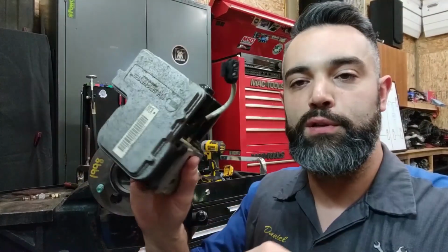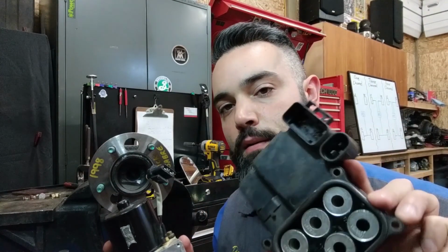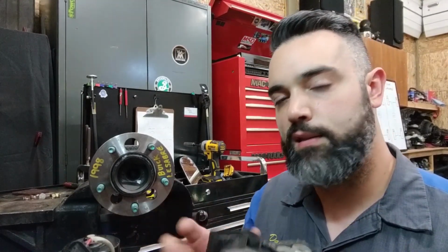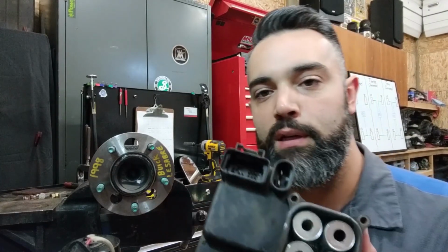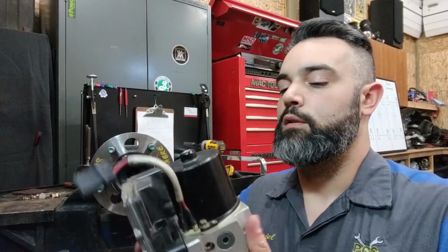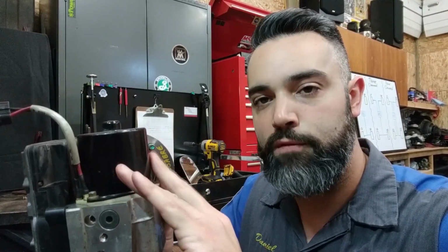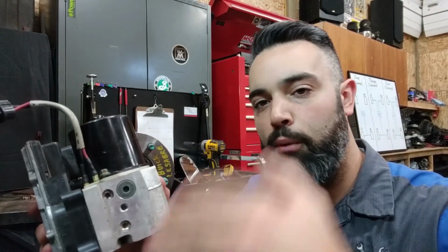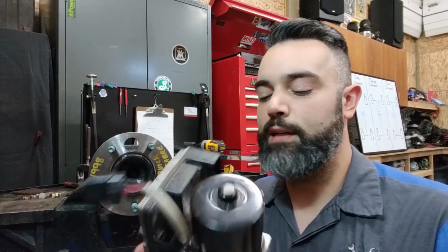Here's an example of one of those units. This is the module side of it, and it's receiving all the information into the smaller pins, the lower amperage pins in here, and then it has power supplied to it on the larger pins. So these are a higher amperage driven device. So this also has an accumulator in it, which accumulates pressure from the brake system, and it's going to use that pressure to help reapply the brakes. It's like a reserve chamber to help apply the brakes.